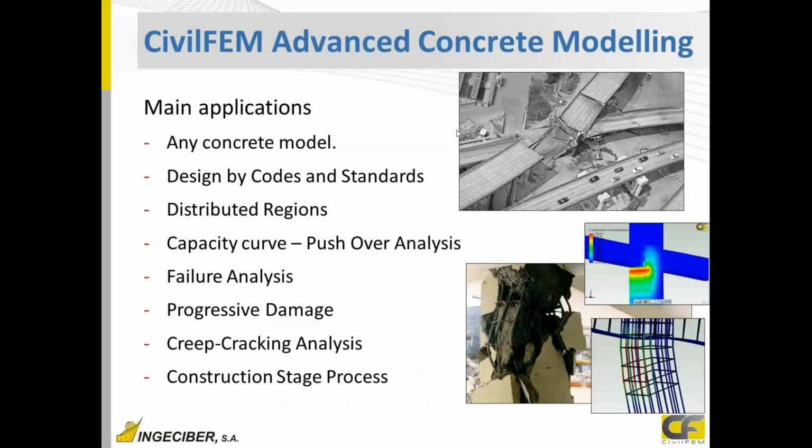And the applications are many. It can be applied to any concrete model. CivilFEM can also design these structures under codes and standards. That is good for slabs, beams, and so on. But in disturbed regions, such as this one called a joint, this type of nonlinear analysis with cyclic loads or any other transient analysis should be done, because code and standards cannot be applied to disturbed regions.